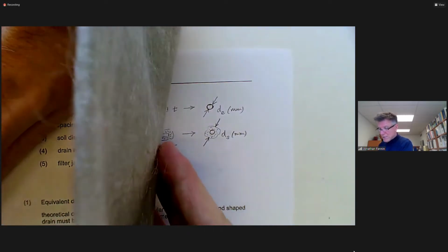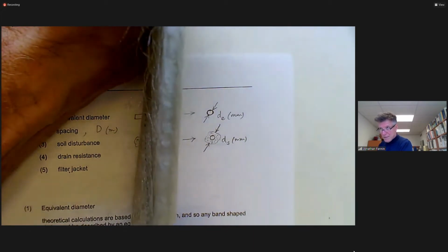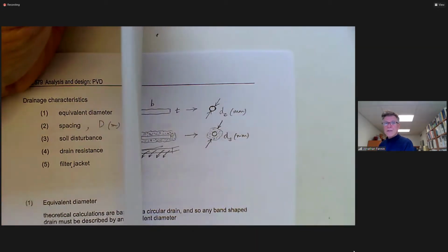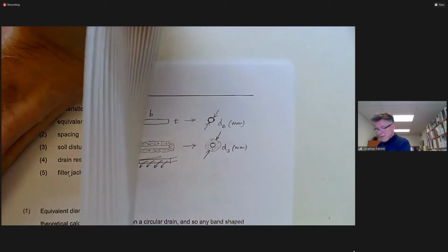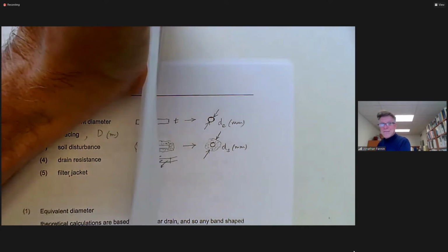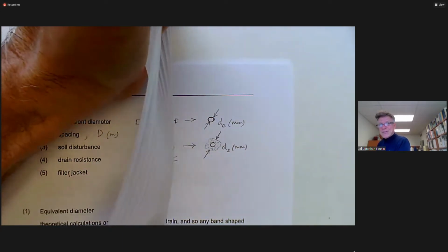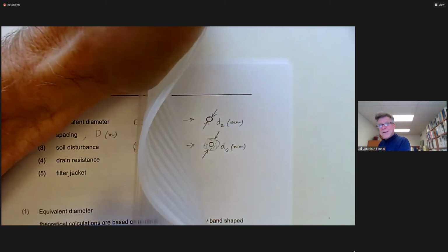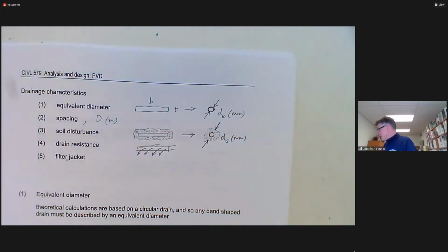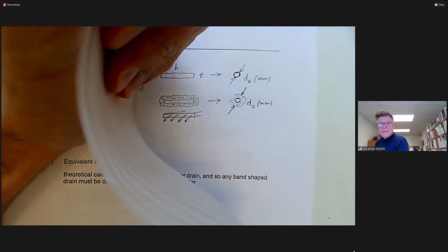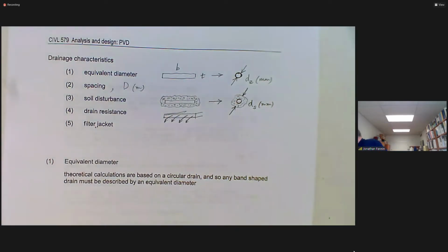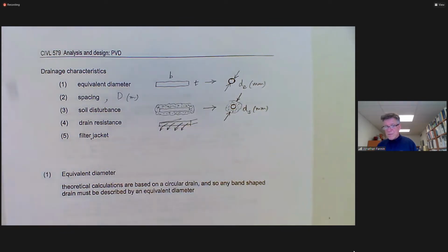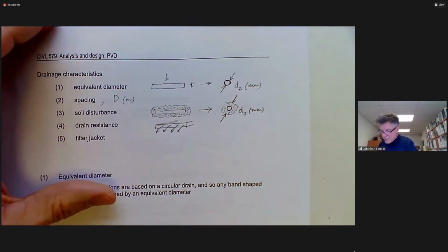As I'm going to try and hold it relatively thin. Actually, let me pull the drainage medium out of the core. It's going to make things a little evident. There's our drainage medium. And now I'm trying to compress it. We're trying to get 3 meters of consolidation settlement going on. And can you imagine what that drain is going to look like after it's been compressed, settled, maybe folded over to accommodate 3 meters of settlement? So drain resistance within the drain, but also because of a change in the alignment of the drain.